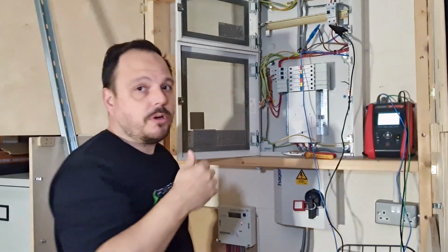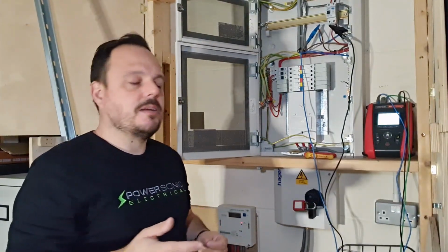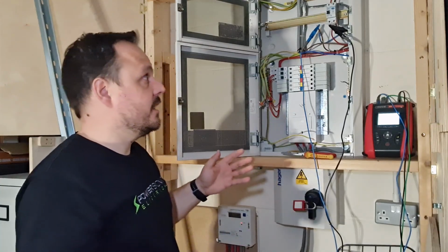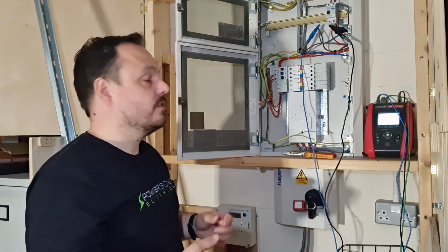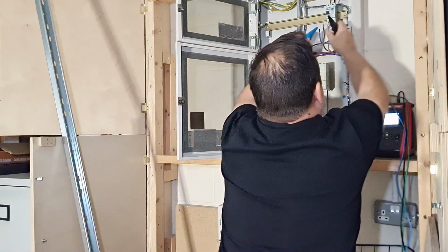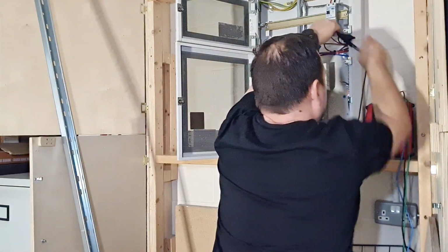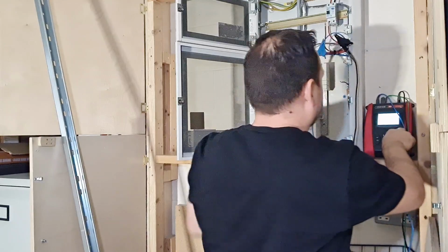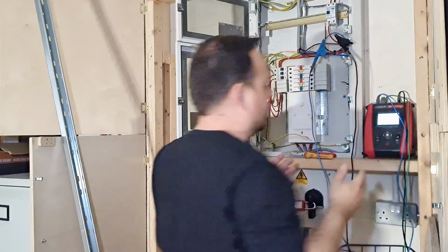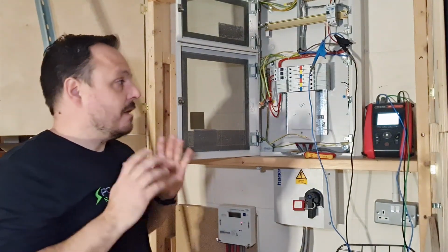And it's 0.13, and again your maths, if you get into this habit of 1.67 times with your typical twin and earths, it won't work on this occasion because we have a 4mm line and neutral conductor and just a 1.5mm CPC. But if we jump onto the neutrals, they should measure out at the same value as the lines, and they do exactly, so it's 0.13. So I'm happy with those now.